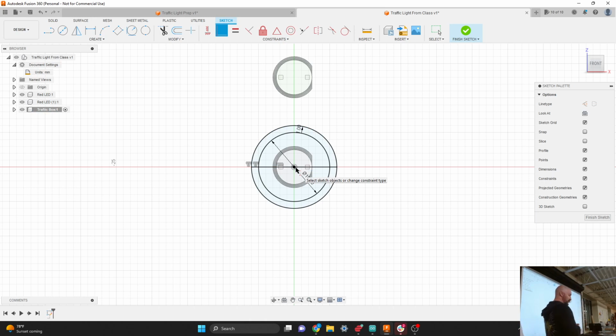The other way to do it would just be to grab your line tool and draw out from the center twice. So I draw from the center. That little weird two blue lines with the three blue angled bits coming off of it, that's actually a horizontal vertical constraint that it's giving me here. So it's saying, hey, that line is straight horizontal. Hey, that line is straight horizontal. So two different options there.